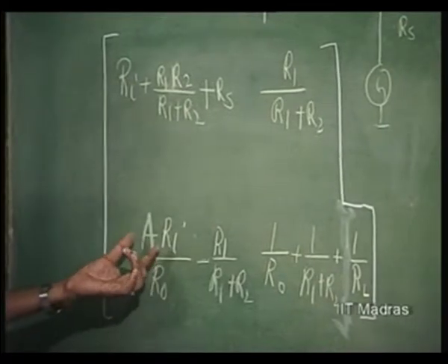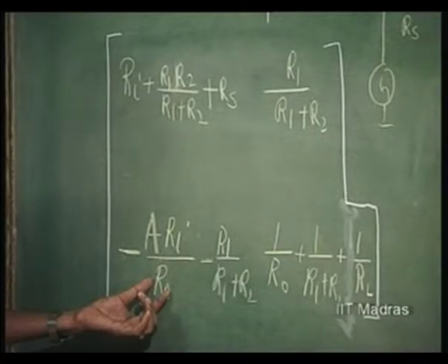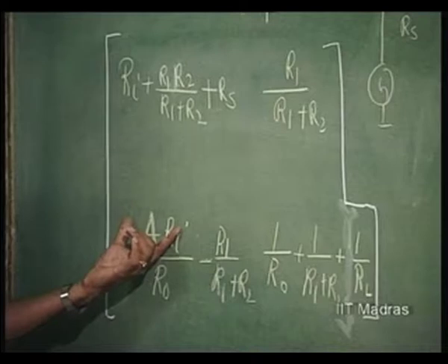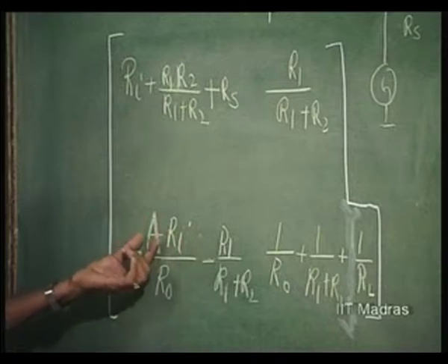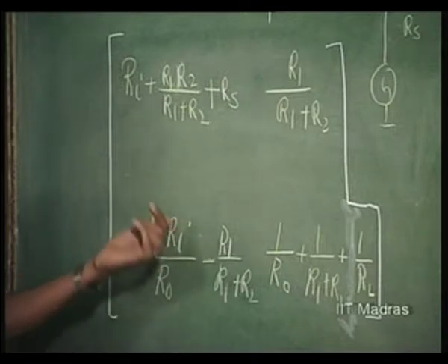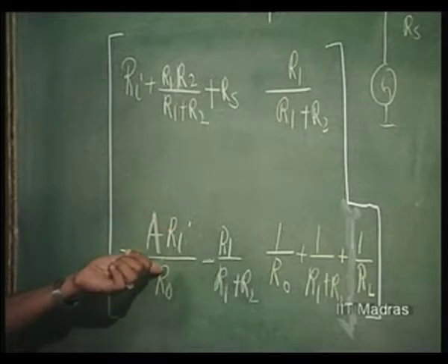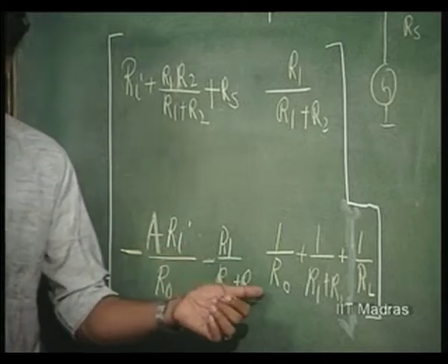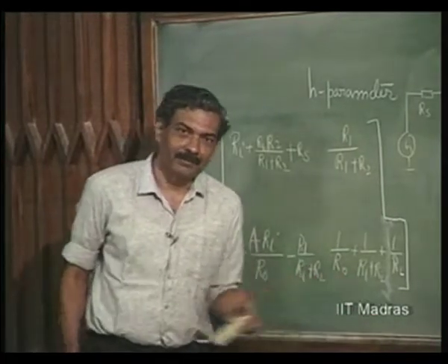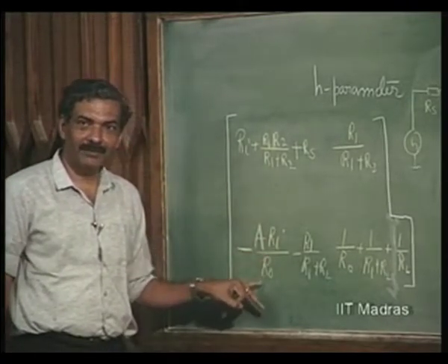But we can see that the other parameters will make this a very huge value. Having R naught equal to 0, Ri equal to infinity and A equal to infinity means this is really speaking infinity cubed, a third order high value. So, this is very huge in a practical op amp itself, wherein A is anyway high, Ri is also high, R naught is very low.